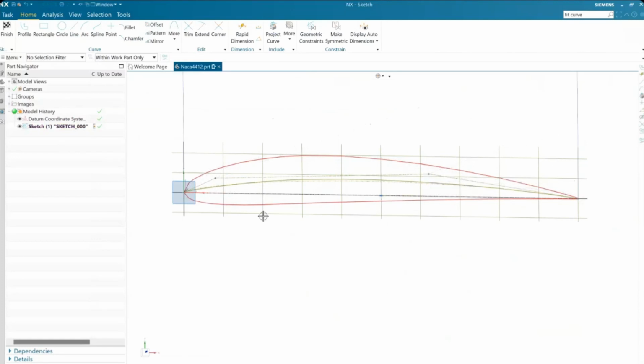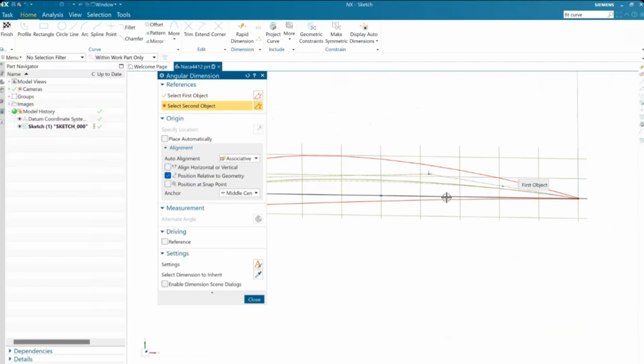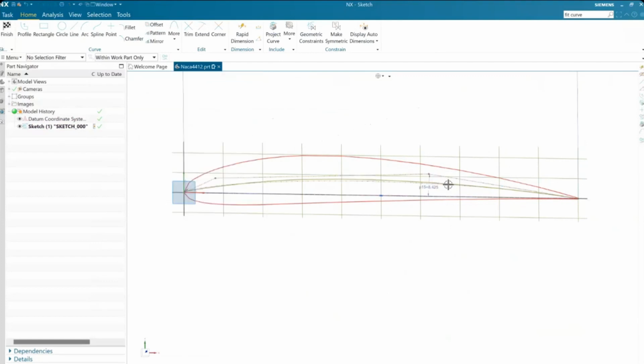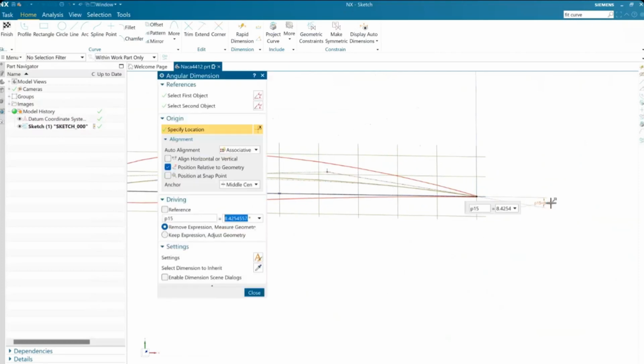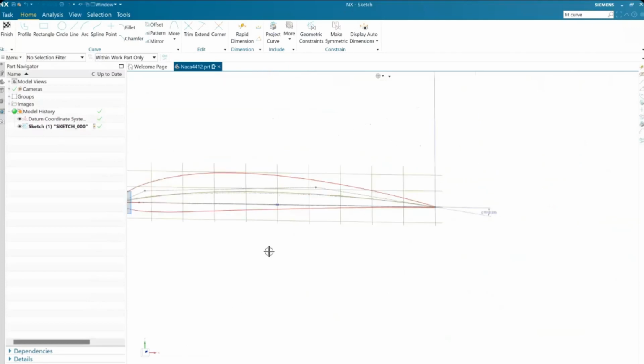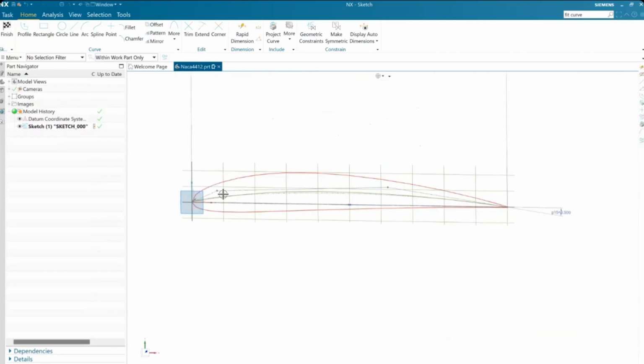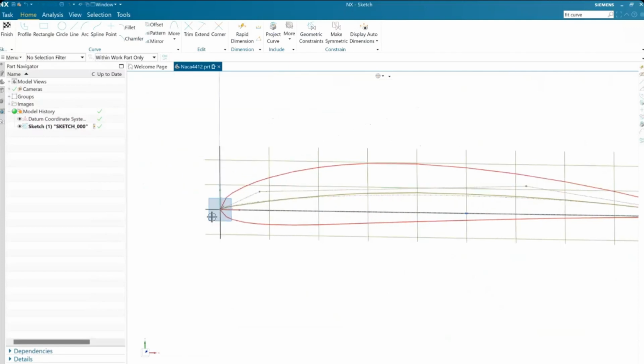Life is good. Now, first we need to dimension everything. What I like to do always first is dimension the angular constraint, and the reason we do those lines at all is so that we can actually select them as angular constraints, and constraints in general. You cannot select the points of the fit curve, or the lines of the fit curve, as I just did. So you will need to put in those lines. For other reasons too, very important reasons.